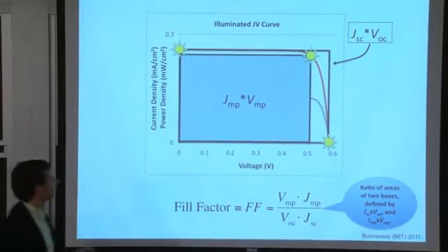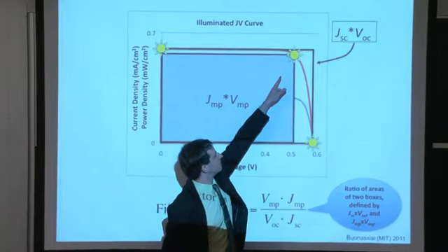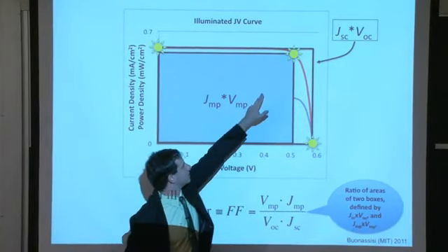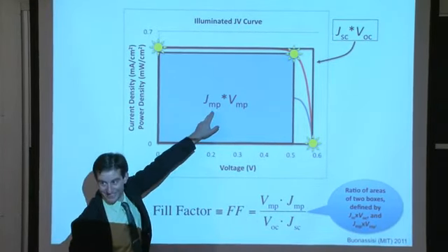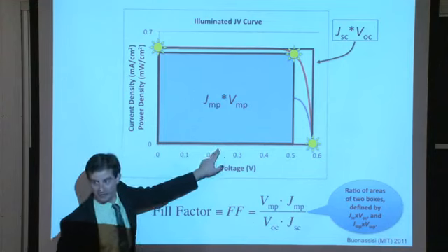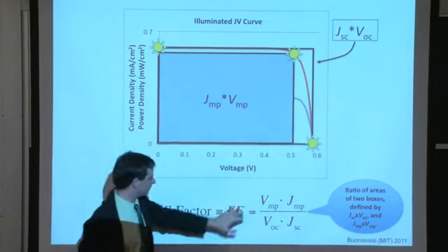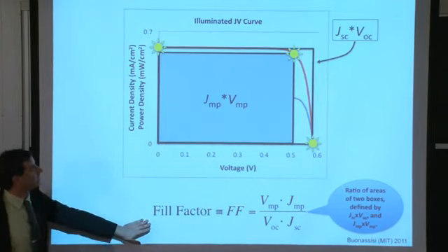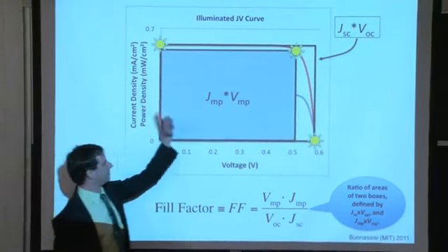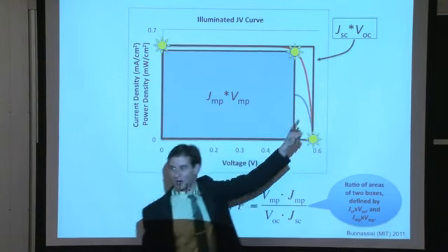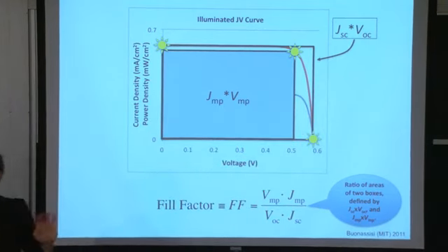If your fill factor is very poor, that means that that sun right over there that denotes the maximum power point is being dragged toward the origin. That means that the area of this blue box is growing smaller relative to the area of this clear box. The fill factor is going down. That means you're filling less of this maximum square box function defined by VOC JSC.